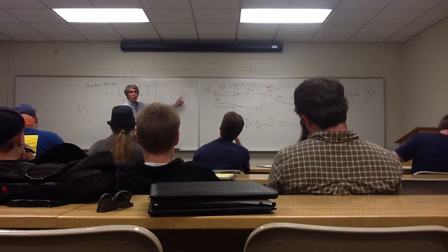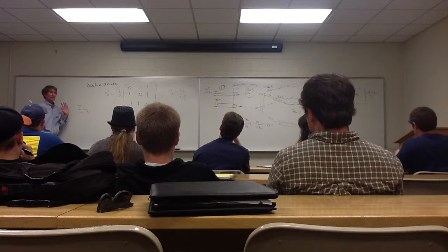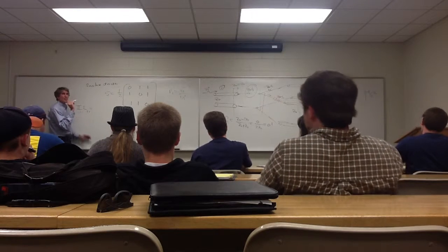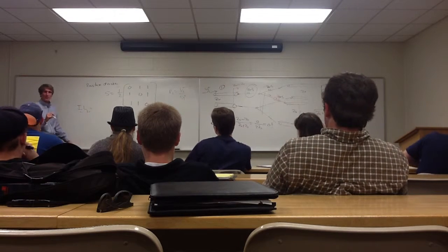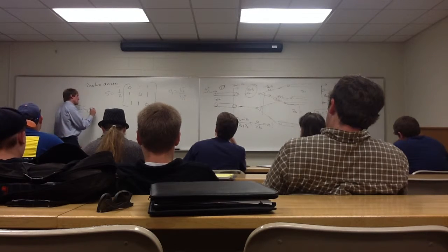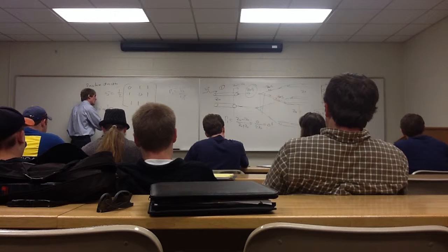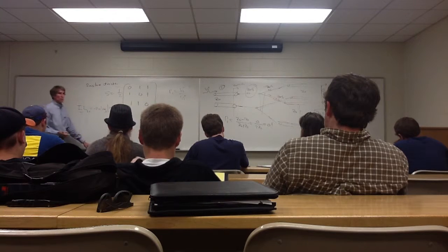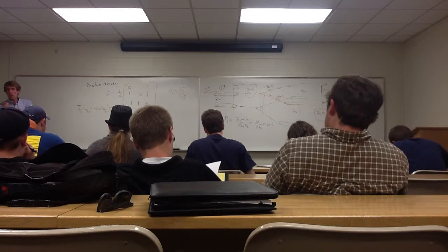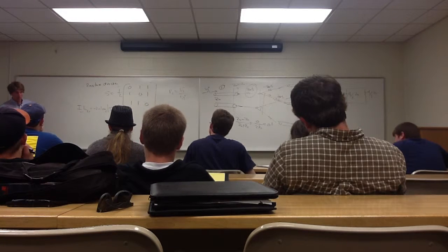When we look at this, this is a voltage, right? I'm saying this because in the last exam there were some mistakes made with dB. So I'm just going to get this out of the way. Here, insertion loss is in dB. But if we look at the reflection coefficient, not the reflection coefficient squared, or the S parameters only, the insertion loss would be equal to minus 20 times the log of the magnitude of S21. S21 has to do with how much voltage comes out of port 2 that was incident on port 1. That's a volt, that's 20 log. Is everybody with me on that?